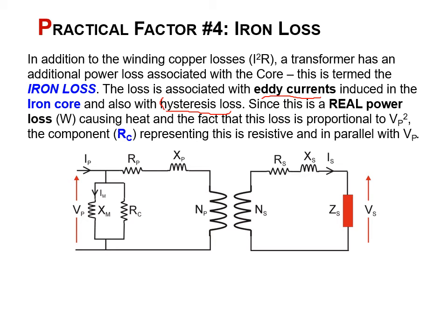So we're going to look in detail at hysteresis loss in the next part of this lecture. We're not going to cover eddy currents in the lectures, but if you look on the wiki, there should be a page which explains eddy currents. The thing about these two is that they are real power loss, and because they're real power loss, they can be modelled as a resistor.